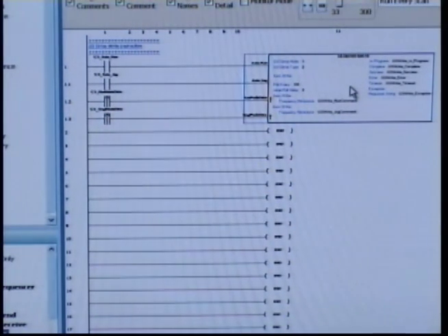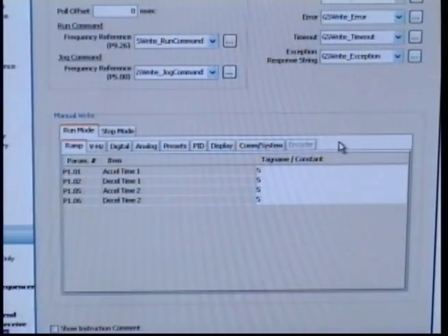And if I open the box, this is the whole thing. I assigned my tag names. I wasn't very fancy. I knew I was doing the GS write command, so everything began with GS write, so I could easily find them. And then in progress, complete. These are all the status bits. I really didn't have to do anything with the polling time because I identified the drive when I set it up. I knew that was going to be node 1.